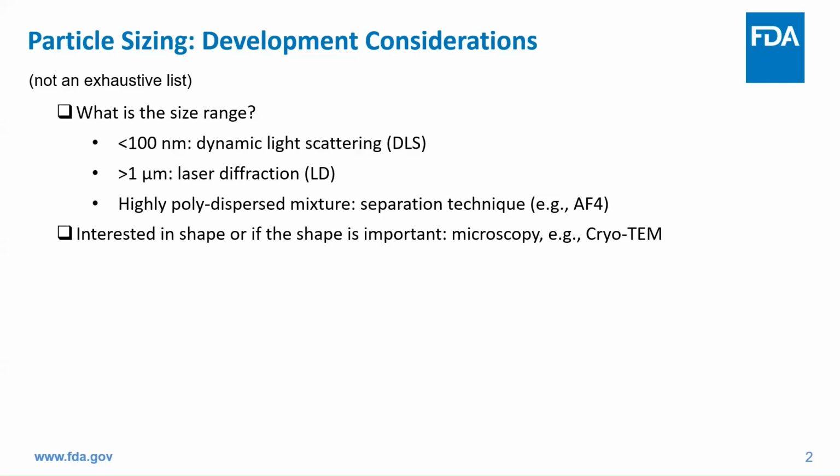So in this case, if the question coming to mind is not only do I want to know the size, again, size may not always be important, but now I want to know the shape, then consider recommending or looking for microscopy data, some of the image data. If the particle is relatively large, the typical microscope will be sufficient, can analyze particles down to 1 micron, 2 micron. The typical microscope is enough.